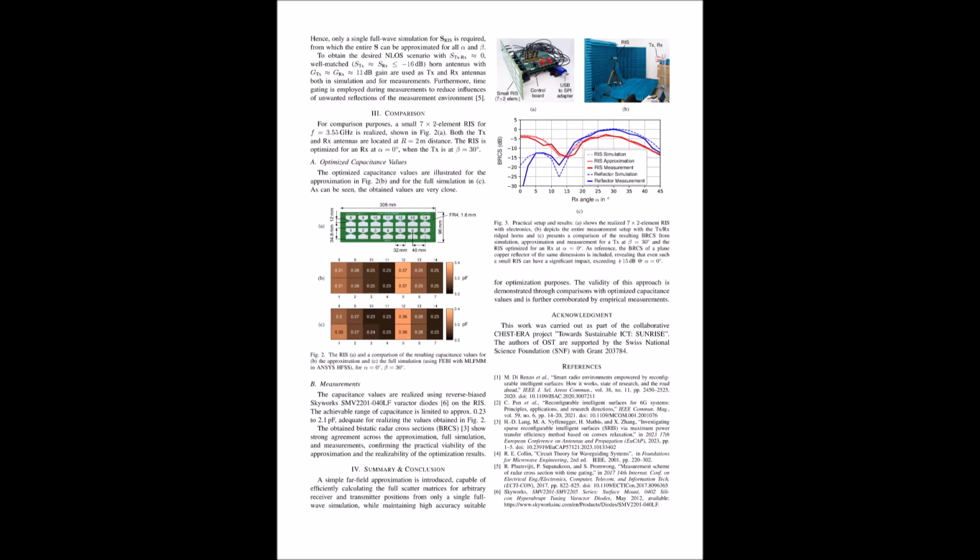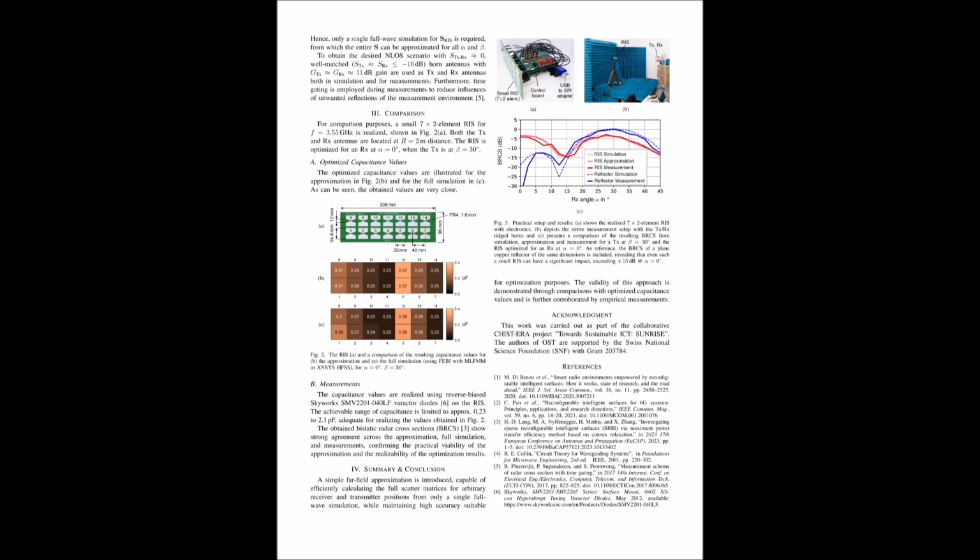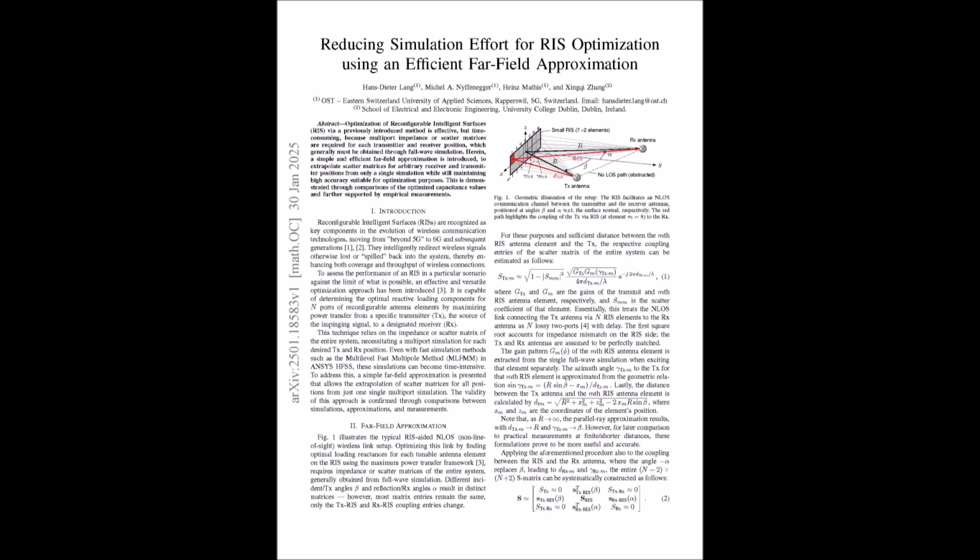Exactly. Careful planning. Now, for the antennas, they used horn antennas for both the transmitter and receiver. Horn antennas. Okay, why those? Well, they have these really focused radiation patterns. They send out signals in a very controlled beam. So that helps reduce any unwanted reflections that could mess up the measurements. Right on. They also did something called time gating to isolate the specific signal they were looking at.